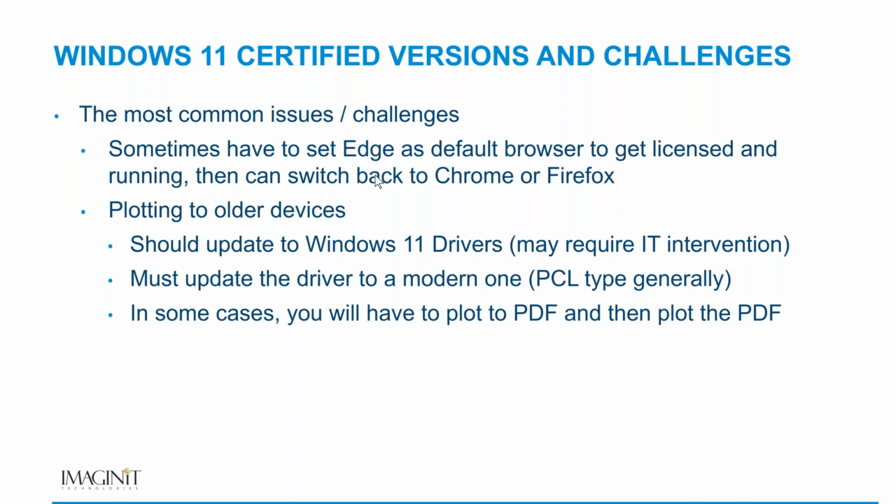Now, the other thing that we've run across a few times here is that if your default browser is Chrome or Firefox, the first time you launch the software, especially 2024, which now requires opening a web browser in order to authenticate and then send you back to your software, sometimes you have to reset Edge as the default browser in order to get that process to trigger correctly once. Then you can switch it back to Chrome or Firefox and it will work just fine.